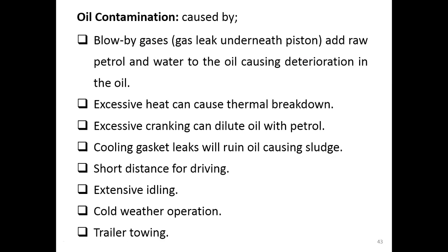And if it leaks underneath the piston, it will go to the oil. So this gas can add what? Fuel, raw petrol, and water, which is the product of combustion, to the oil. So it can damage the oil quality, so our lubrication oil is contaminated.